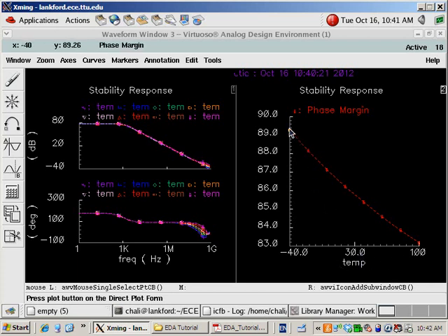Okay. So as we can see, if the temperature is increased, the phase margin gets smaller, right? So for analog designers, it doesn't mean we design something with the original setup and then that's finished. We have to worry about temperature corners. Like in this case, the real design case we have to worry about is the case at 100 degrees, which is the most challenging one, right?